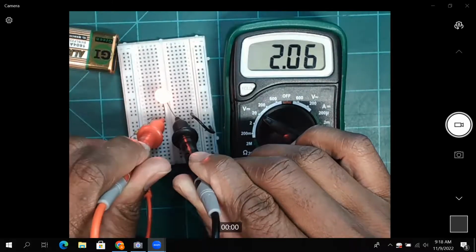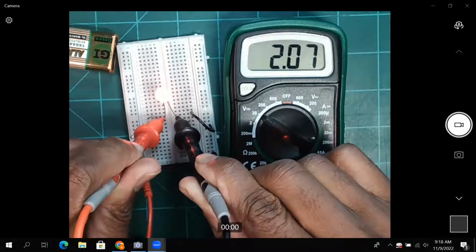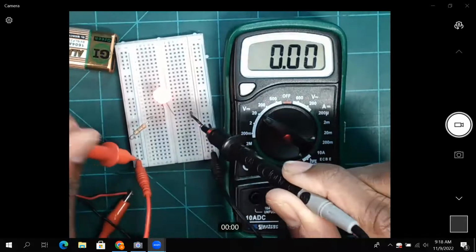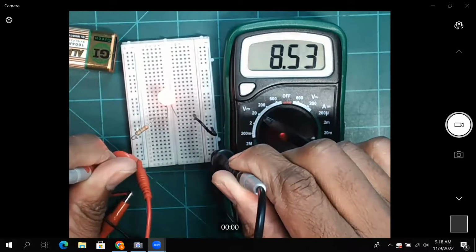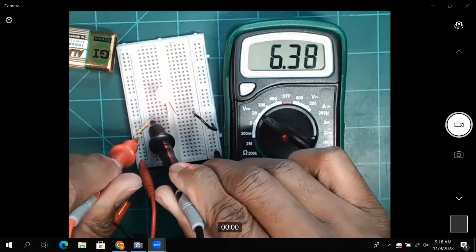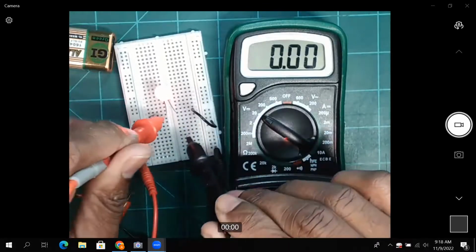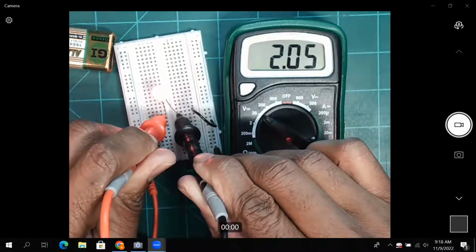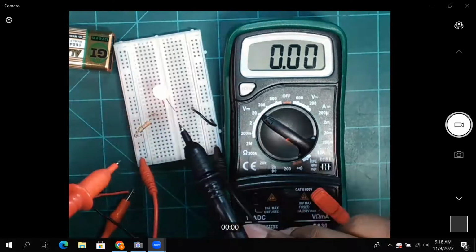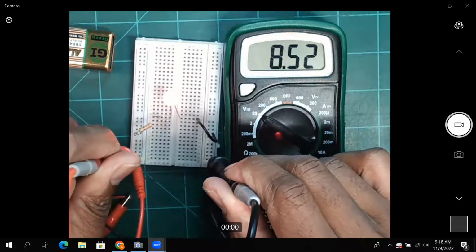All right, so according to Kirchhoff's voltage law, the sum of the voltages is going to equal the total supplied voltage. So notice that I have 8.5 volts being pushed through my battery. From my battery, we'll say I have 6.3 volts going through my resistor, and it drops. And we have 2 volts. So if you added the voltage that's going through my resistor and through my LED, it will equal the total supply voltage of 8.5. Okay, thus Kirchhoff's voltage law.